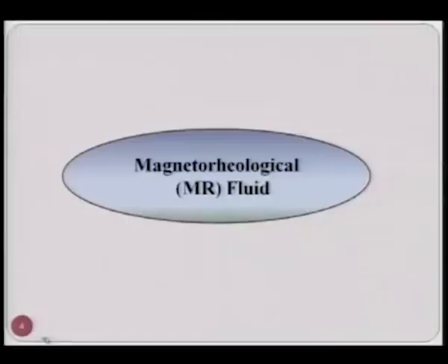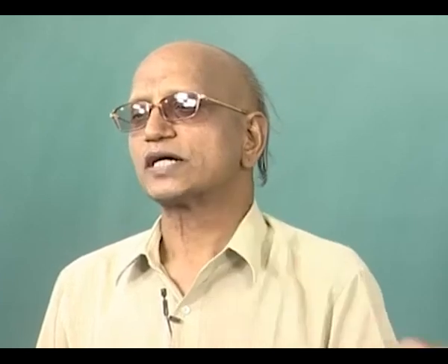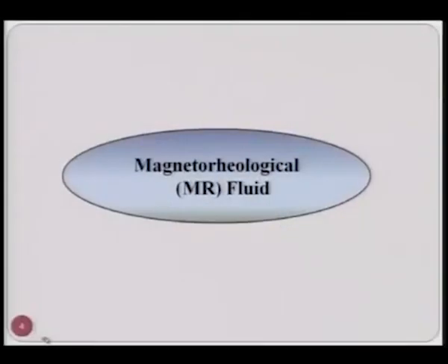and size constraint. Also, apart from shape and size constraint, they cannot give you a nano level finish in complex shaped components or components which are made of very hard materials. For this purpose, we have to go for advanced finishing techniques, and magnetorheological finishing is one of the advanced finishing techniques. In the magnetorheological finishing process, the medium that is used for finishing purposes is known as magnetorheological fluid, or I will be commonly calling it the medium.